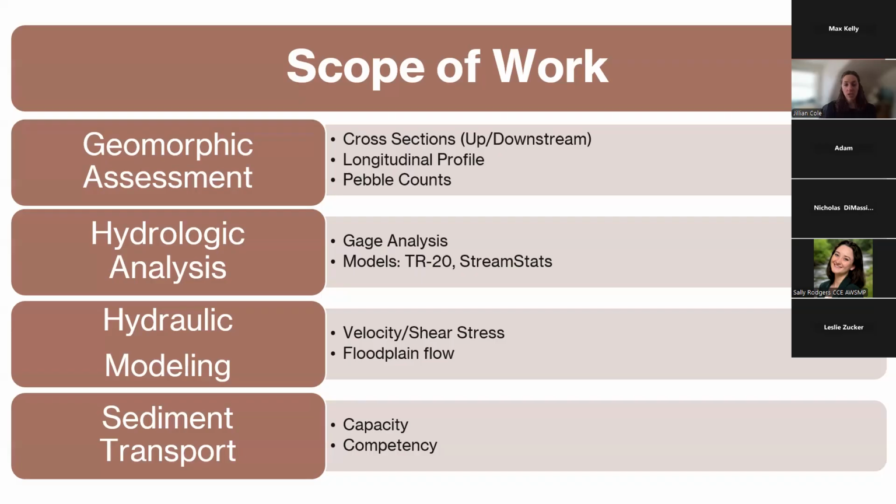There's also situations where it's really valuable to do two-dimensional modeling instead of the standard 1D. Two-dimensional modeling allows a much more detailed depiction of flow dynamics, as well as discrete changes in velocity. It also better defines out-of-channel flow. So if there's a large floodplain area or there's a lot of complexity in the site, a 2D model will